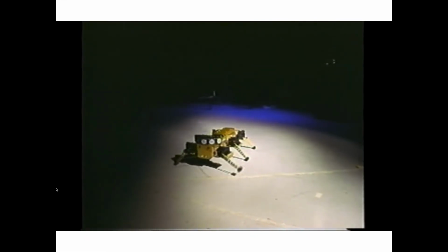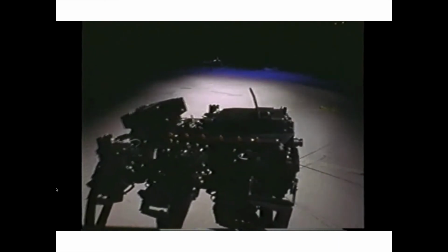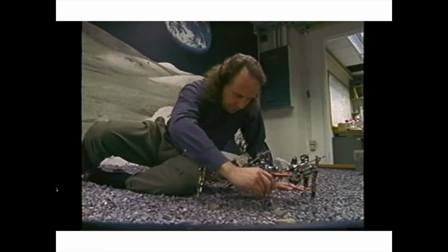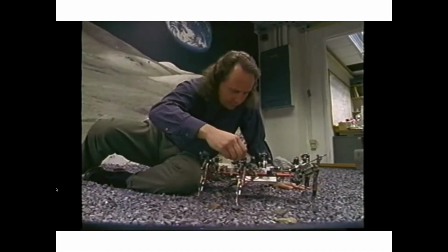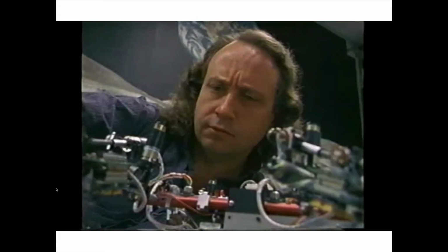Brooks' insect robots aren't intelligent the way we think of humans or even computers as being. Instead, they operate on patterns of behavior. When you turn them on, they're brainless. But with each step they take, they learn how to adapt to their environments. Rather than having a standard central controller, these robots have separate layers of behaviors that are independent but which communicate. No advanced behavior can start unless the simpler ones are up and running.